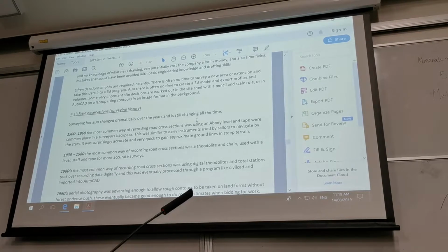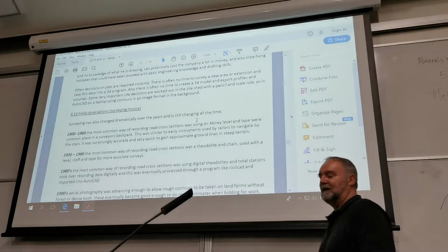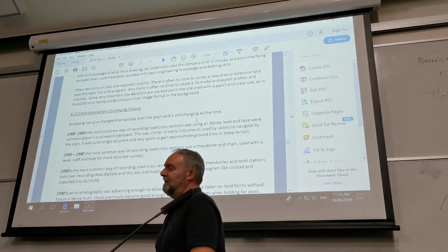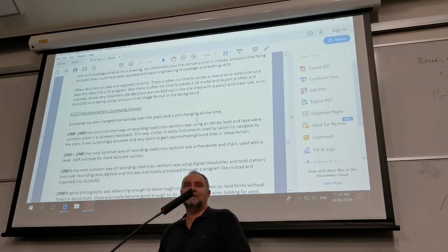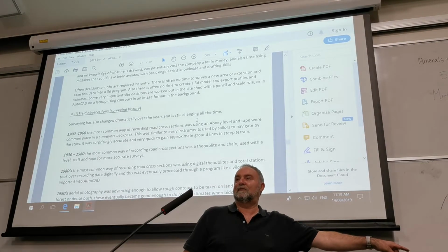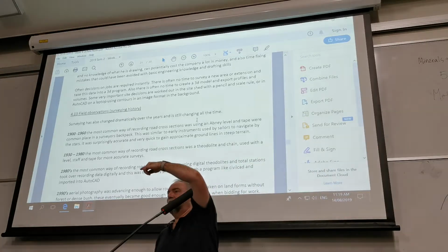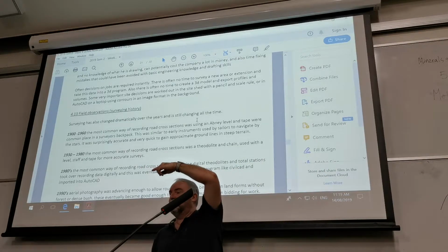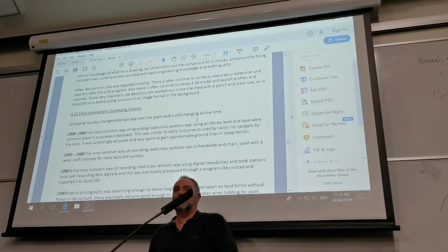Normally, if you're going through thick bush, you have a bushwhacker that you're clearing it with, so you've got that in your hand. And so to carry just a stick and an Abney level was a very quick and a very accurate way of doing it, really, for those days. You think of taking total stations up through the bush, carrying that in a backpack. You know, the surveyor is still way down the bottom of the hill taking his first 3 shots. And you've gone over 2 hills with the Abney level, and you've got a very good idea of what the countryside's like.